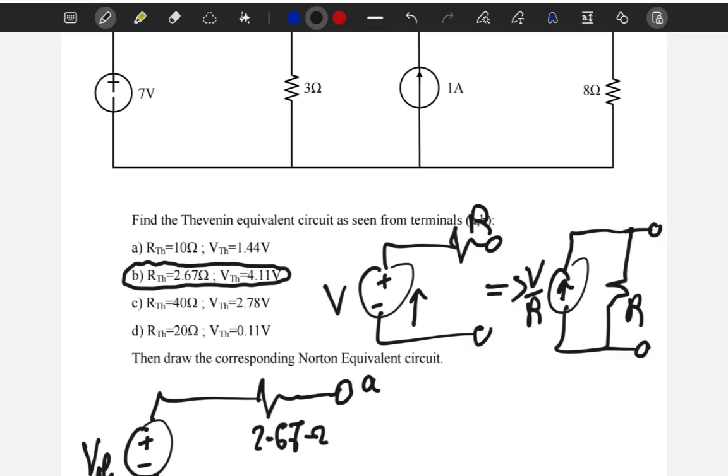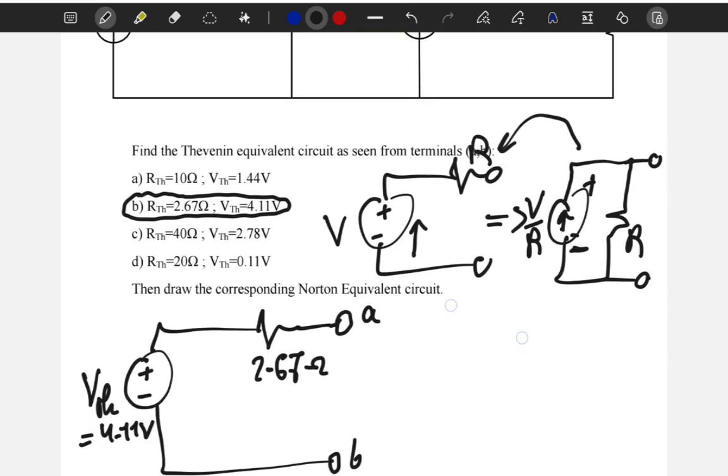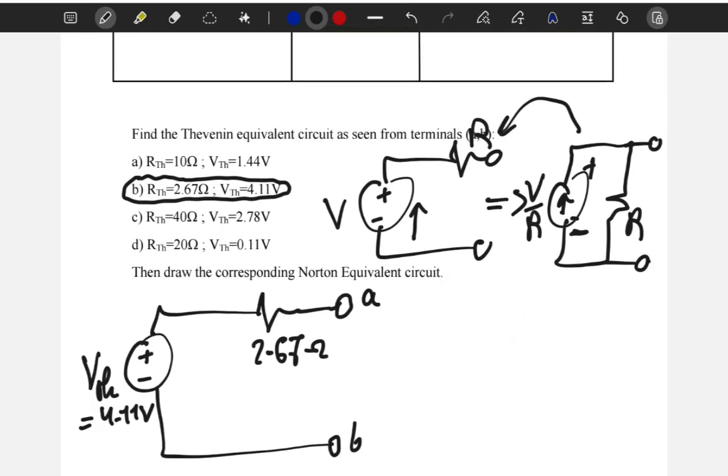The resistor is in parallel, and obviously if I want to go from this back to this, I can. The current source I multiplied by R becomes a voltage source, with the negative terminal at the back of the arrow, so there's a minus here and plus at the tip of the arrow. So I'm back to V, and the resistor, instead of making it in parallel with this source, I make it in series. So basically finding the Norton equivalent circuit is applying this source transformation.